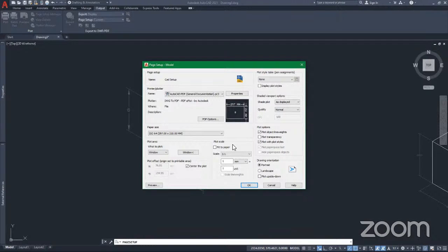If you use centimeters or millimeters and you're doing 1:1, in this case, it's millimeters, right? Millimeters are not inches. And you do 1:1, it means that after you've done your drawing or your plotting, someone can take a meter rule and measure that particular drawing, and each unit will be equal to 1 millimeter in real time. Do you understand this?